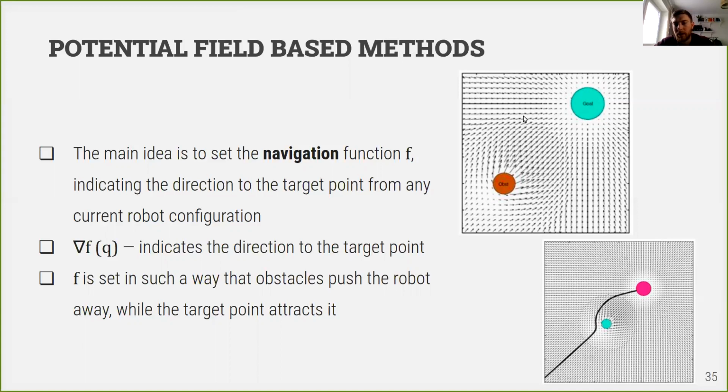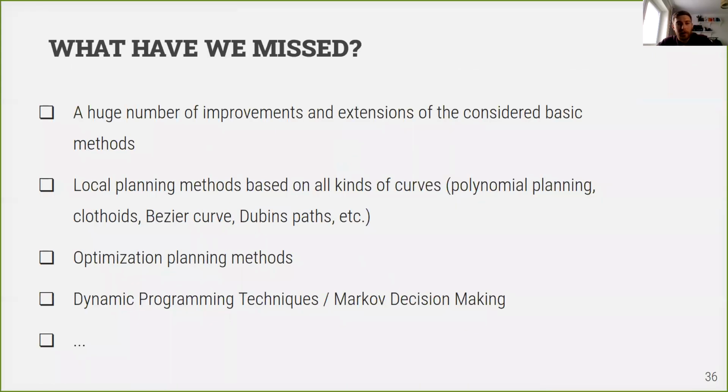So you can imagine the situation that in this potential field, our goal is usually a global minimum, but it can have local minimums, and sometimes if the robot falls into a local minimum, it can be stuck. So we need to find some modifications to this classical algorithm to make our robot unstuck and to move to the goal. So this is just a basic idea of potential fields. We will not discuss it in detail. And that's basically it for today.